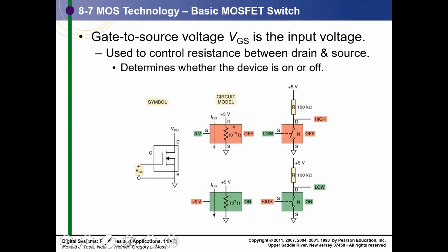If you connect your gate to 0 volt, there is no conductivity channel, and it becomes a high resistive region between source and drain, and therefore it behaves like an open switch, which is off. And if I connect on the gate a logic 1, which means the higher potential VDD, the resistance turns down. There is a channel, but a channel also has some resistance.